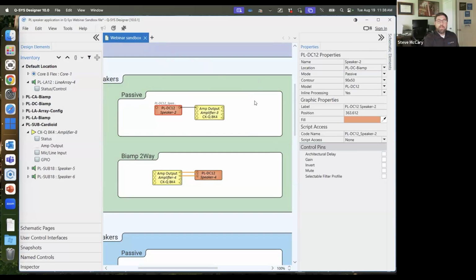Why are the recommendations only for the 4-channel amplifiers? Can you use them with the 8? Mainly because of the output power you can get for the 4 channels. We suggest the 8K4, so 2000 watts per channel on 4 boxes of the line array.